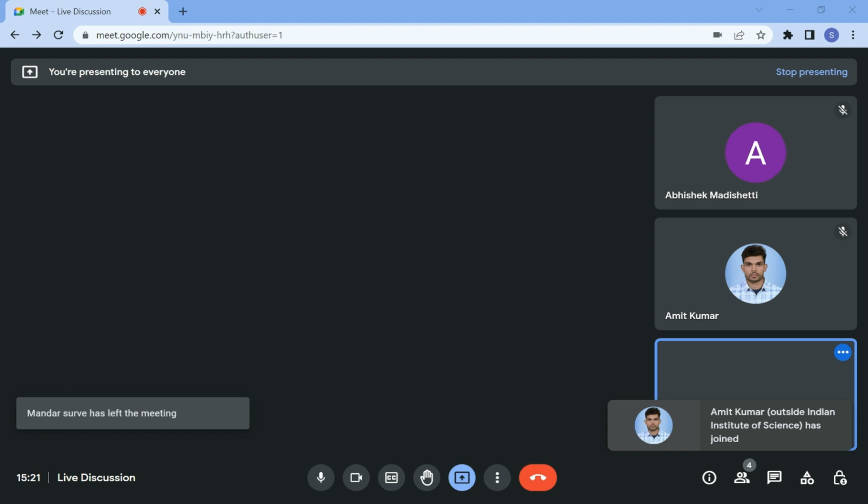I know that this is at 45, and from this projection itself, I also got that this is the radius of the circle in vertical plane. So this red circle that I had traced here, that is the radius is 80 cos 45, which I'm going to pick up from here, project it here, and draw an arc which intersects this line which is at 55. So then you get the point B.